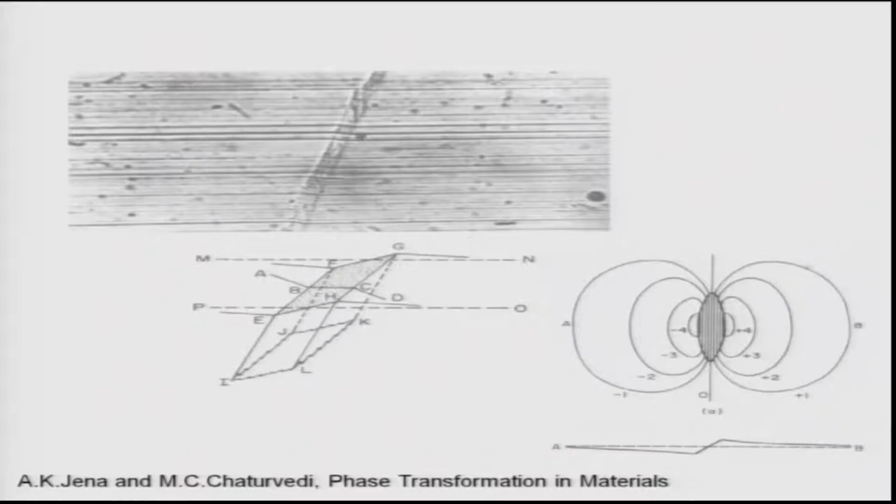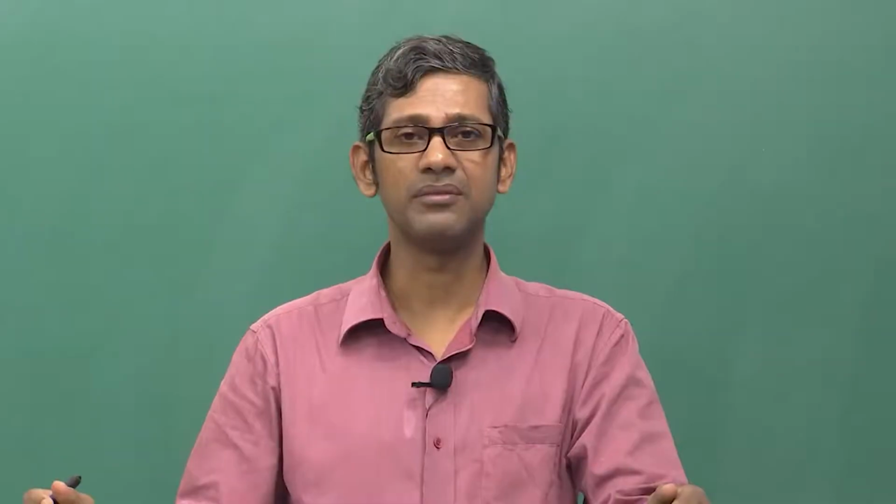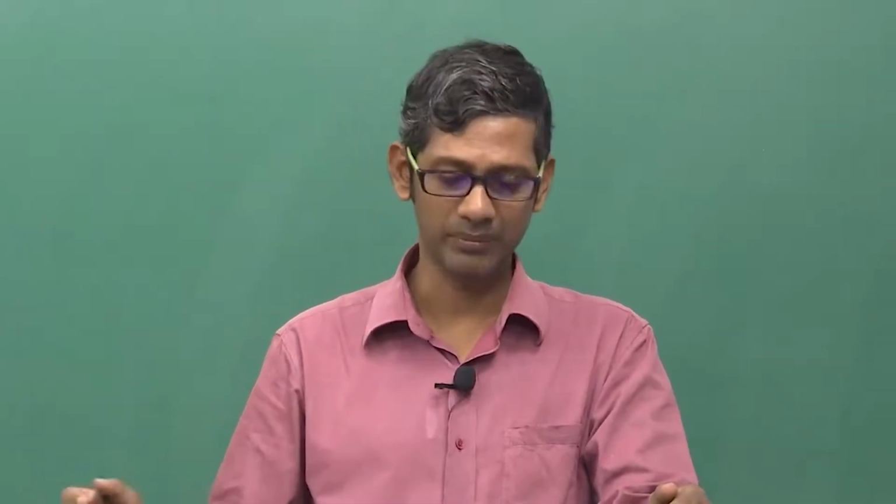As you clearly see, before the transformation of martensite, some scratches were made on the surface, and then the steel was heated to a high temperature and quenched in water. So, obviously martensitic plates will form on the surface, and this normally creates surface relief. That means the distorted plane comes out from the surface and creates a surface relief. That is what is seen there.